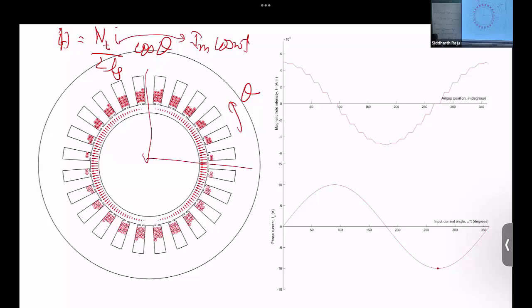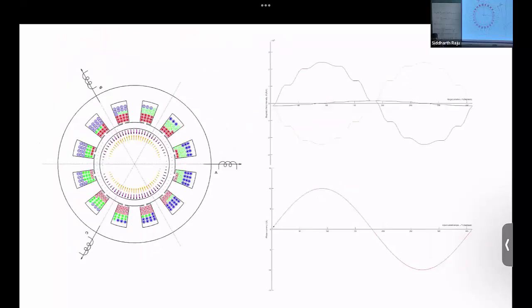So as the current changes in this plot here, you can see that the H field and the B field effectively in the air gap just shrinks and increases, goes up and down. And we notice that this is the same as the standing wave that you have seen in the physics experiment when we do sound speed estimation. And there we have a forward traveling wave and a reverse traveling reflected wave which interfere to create a standing wave. In our case, we are doing the reverse. We do have a standing wave in the air gap. We recover a separate mathematical forward traveling wave and a reverse traveling wave through a pure mathematical operation. So that's the equation that I've written down here on the board, and once I lift the screen, you'll see the rest of the equations for those. Right?